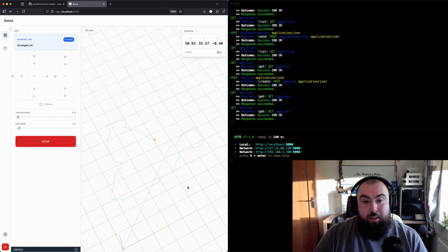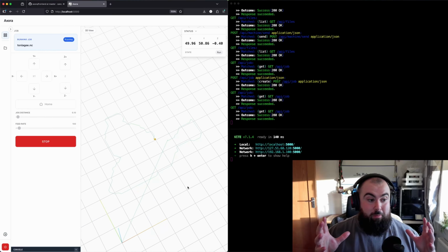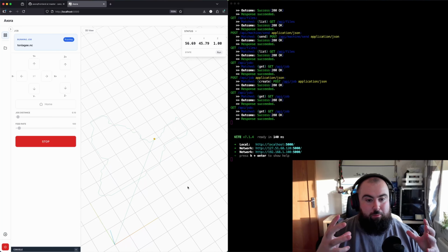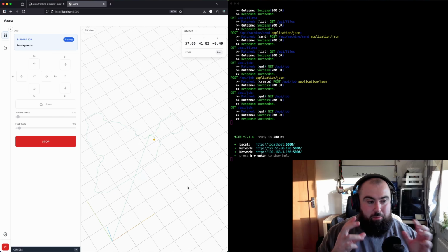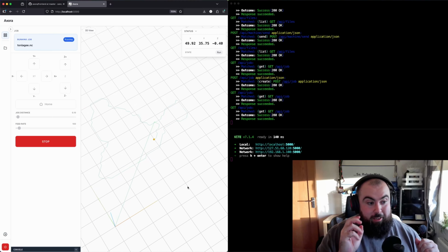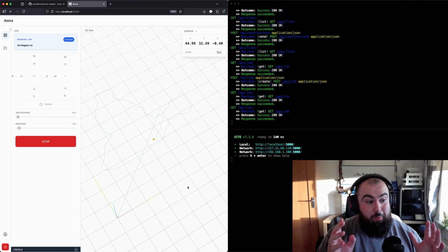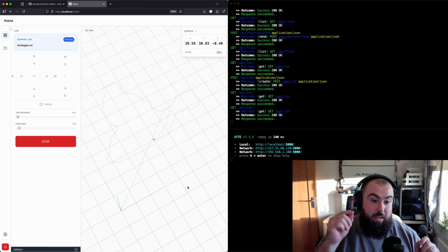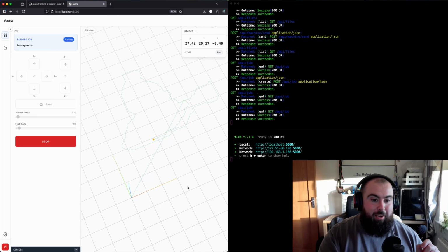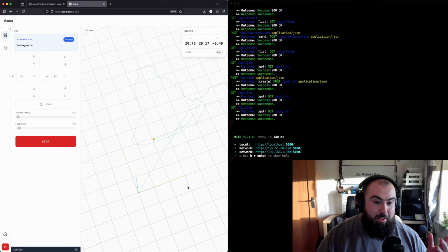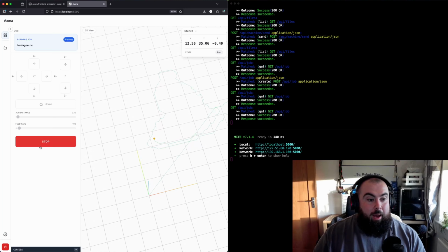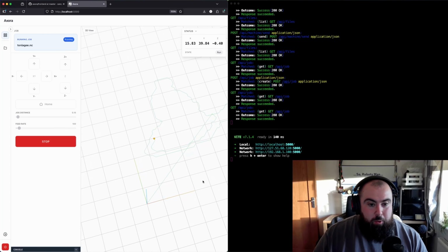So with this tooling setup right now, I'm pretty confident that I can take an engraving job that I've done up in Fusion, I can throw the job, I can upload the G code onto the system, I can set it up on the machine, I can hit this button and I know it will execute this G code and it will show me the progress as it's going. And I can emergency stop. I can hit this button if I need to stop it.